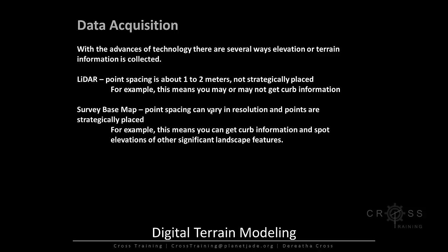If you recall, LiDAR is something that's collected over a very large area. The points are not strategically placed. The spacing is between 1 to 2 meter resolution. And then I said that with survey base maps, the point spacing can vary in resolution and points are usually strategically placed, and this is dependent upon the survey method. So that's what I'm going to focus on a little bit, the second category, which I called survey base maps, really generically and vaguely.